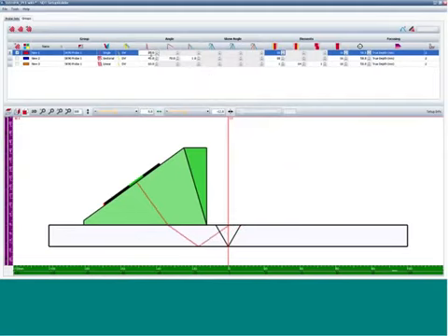Okay, this one A-scan starts on element number 30 right here, and uses 16 total elements. So 16 elements times the pitch of each element, 0.6, equals 9.6 millimeters. So my aperture here is basically that of a 10 millimeter probe. Okay, I'm limited in my configuration now. I cannot type in a larger number than 16.